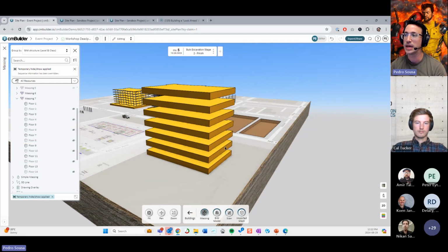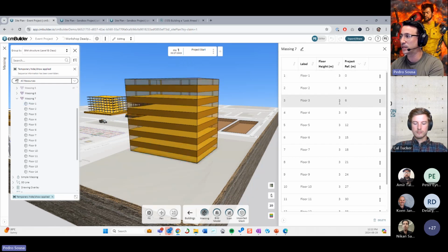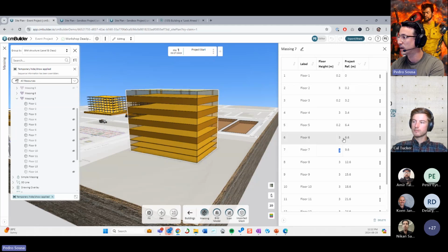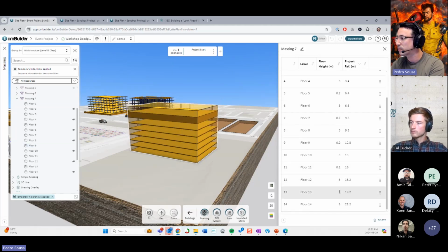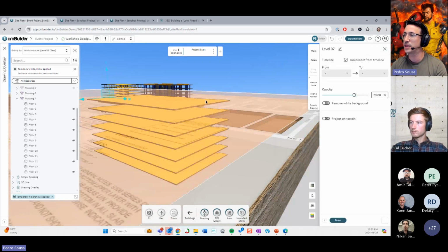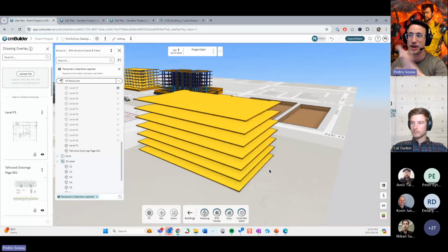So if I keep going over here, these elements won't show up. And then when I open the table to edit this, I can put in the slab thickness on the odd levels, right? So I'm going to put in a slab thickness of 20 centimeters over here. Maybe this is too small, but let's just pretend that our concrete is the best concrete in the world. And now when you do that, you have intermediate slabs created like that, showing just the slab edges, right? So now I have a model that shows all my slab edges and so on and so forth.